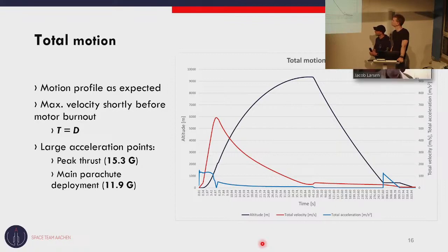All right, as a continuation of that, one thing I couldn't see from your design is: do you have a sharp edge on the opening of your parachute bay? This is in conjunction with the possible backflip that this rocket is going to make. Some of the failure modes that have been seen in these cases are that a sharp lip on the recovery bay either has the potential to cut the shock cord, or the shock cord will tear down through the parachute compartment like a zipper, possibly damaging the shock cord in the process. Have you been considering this failure mode?